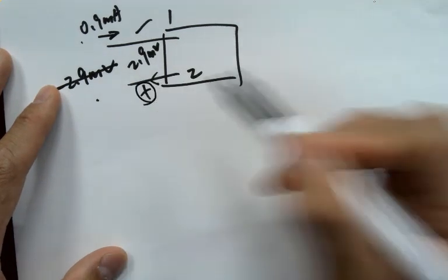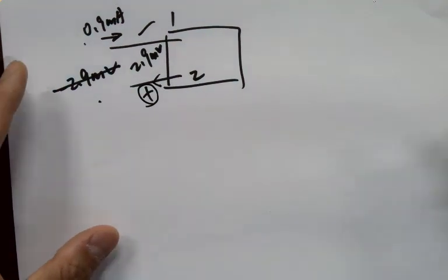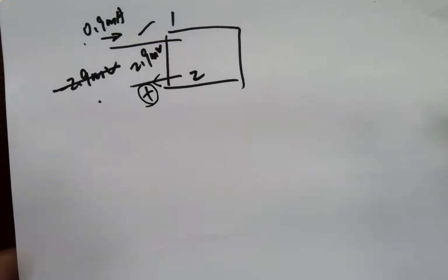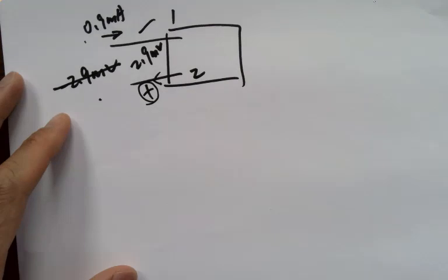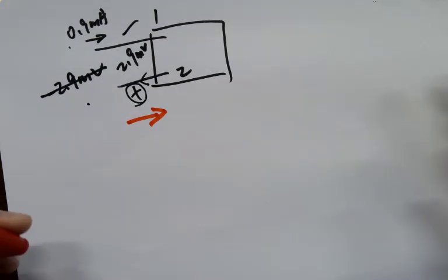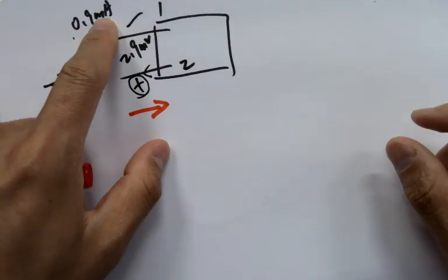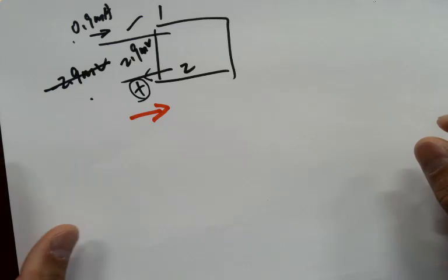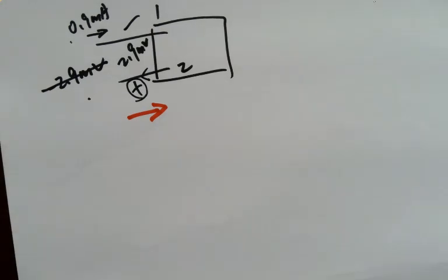So if you look at the anode, it's actually delivering current to the outside circuit. So it's delivering and supplying. It will be negative power. So if it asks you, what is the current entering terminal 2? That'll be negative 0.9 milliamps. Okay? Cool.